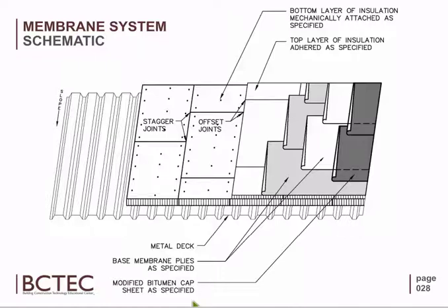Metal decking, not so far, 20 to 30 feet, depending on how big the decking is. Gyp deck, that's pretty common. That'll just leak through. It's like drywall. So you really have to focus on your decking type and where it's at, and also what type of roof system it is. If it's a BUR 4-ply roof, it's got a lot of roofing to get through and migrate its way down. And if there's any slope on the roof at all, you've got to be experienced to find that leak.